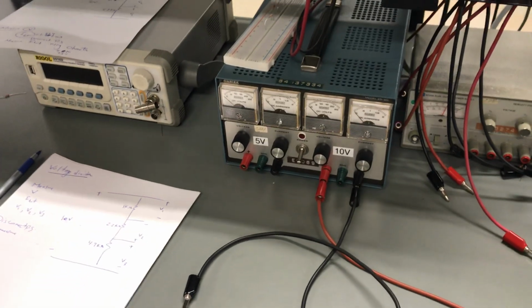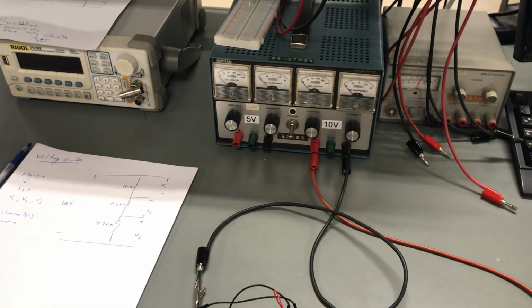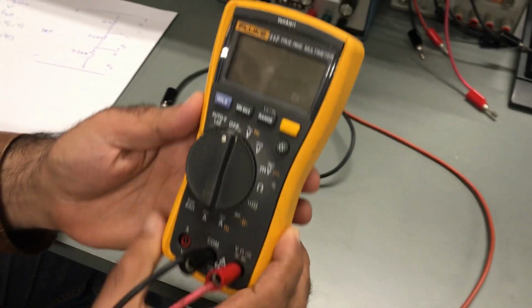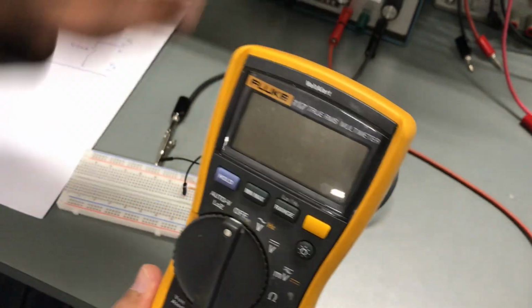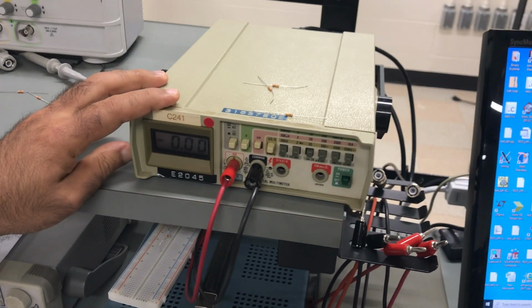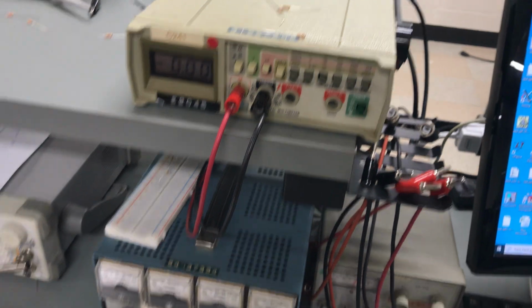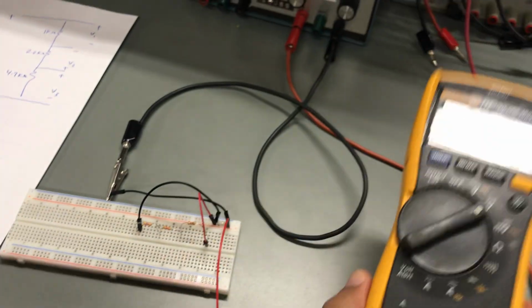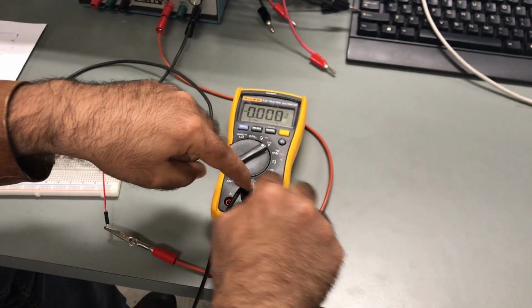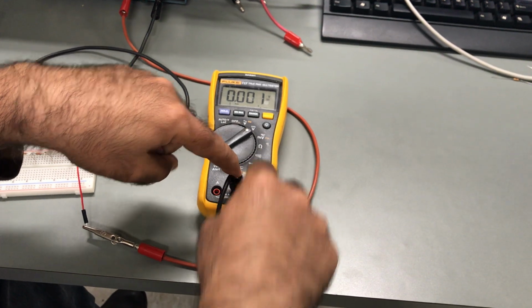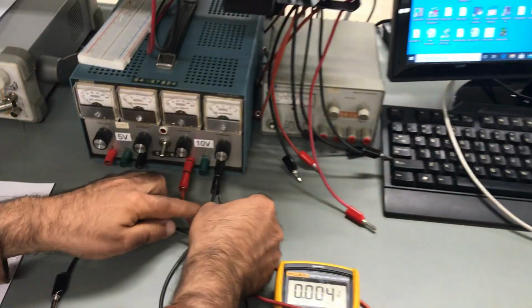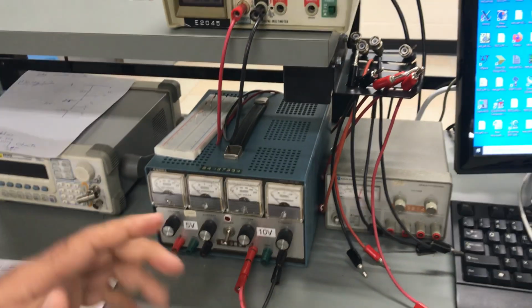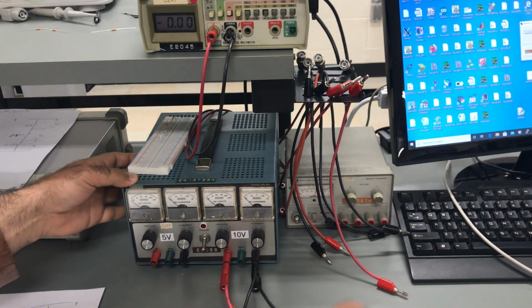So what is the next step? The next step is to connect a voltmeter to measure the total voltage. This is the multimeter that I showed you before, and I'm going to use two different multimeters, this one and at the same time this one, to save my time. I'm going to use this one as an ammeter, and I'm going to use this one as a voltmeter. So I will adjust this one to measure DC volt, and I will connect the terminals between these two spots, and I will connect this one to the power supply to see the voltage that I'm feeding my circuit by.